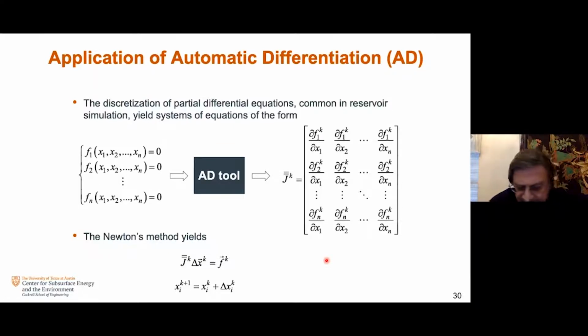The other thing is that when you're solving these partial differential equations, because you have sets of equations, you choose sets of primary variables versus secondary variables. Depending on what you choose for your primary variables to solve the equations, it varies, and different formulations come into the picture. Sometimes one formulation works better for a given process. That gives the goodness of the AD tool, because you could have many of these formulations tested and pick what you want for a given problem.